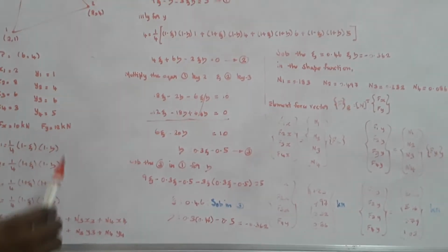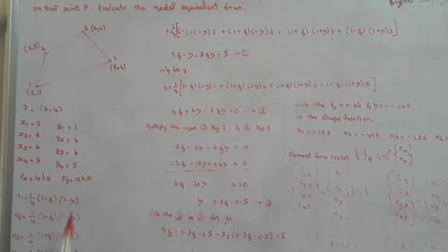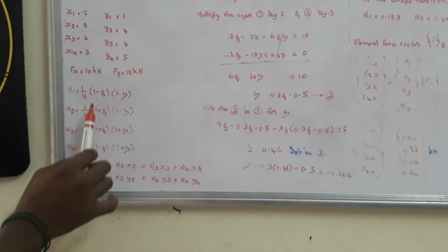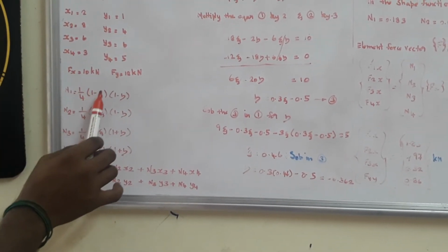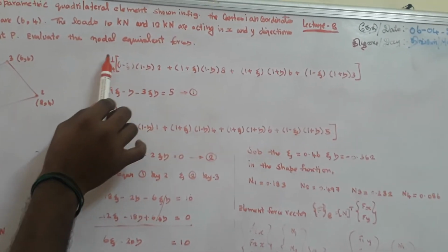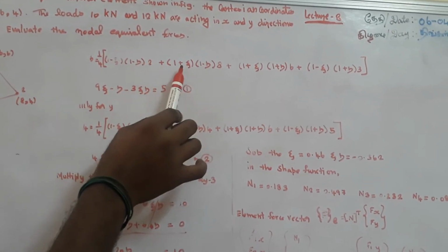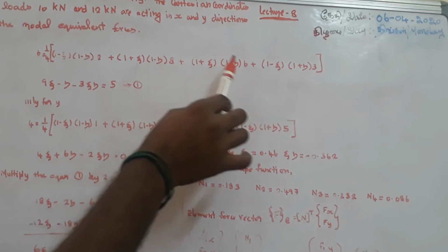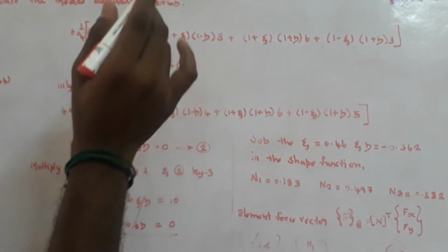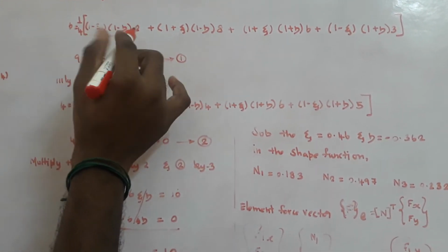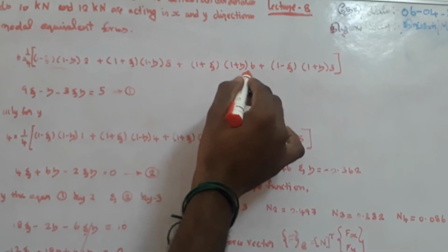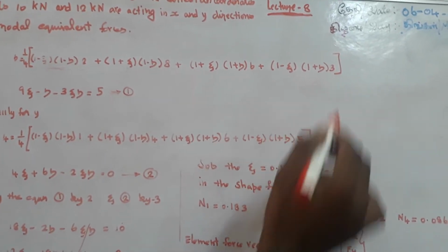Then the data given to solve the problem starts from the Cartesian coordinates. Because the x coordinate is given and the y coordinate is given, with the shape functions we have to find the corresponding epsilon and eta values. For the x direction Cartesian coordinates, x is equal to N1 x1 plus N2 x2 plus N3 x3 plus N4 x4, and these are the corresponding values of N1 and x1, N2 x2, N3 x3 and N4 x4.